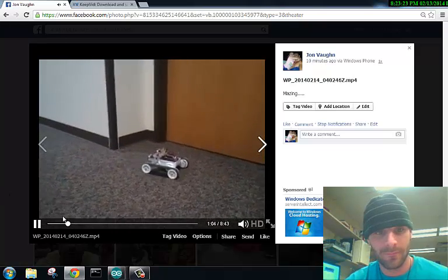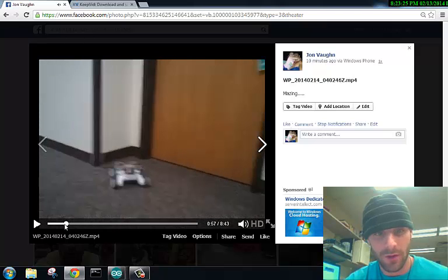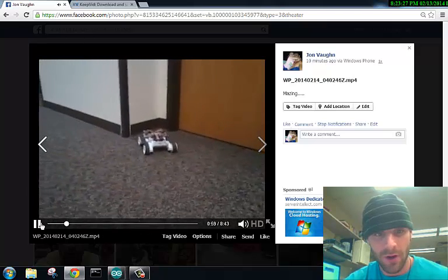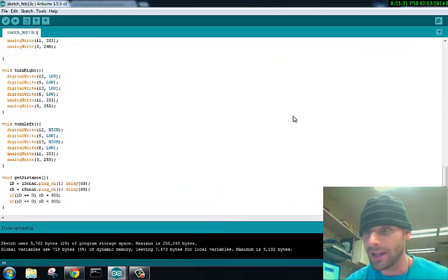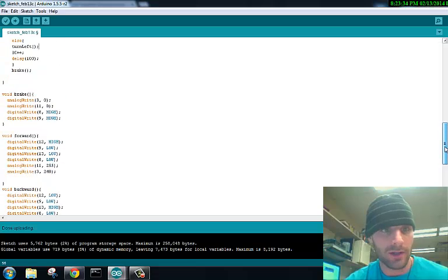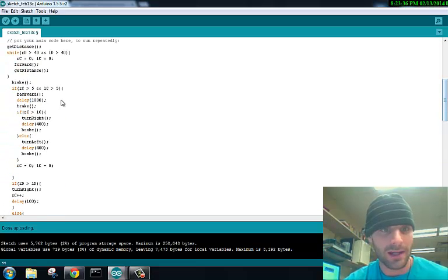There he goes. Now look right here and I'll show you what's going on. So you see how he's rocking back and forth there? Well, that's what this code up here does that I showed you. This code up here checks if right count and left count are both greater than 5. It checks exactly for that rocking distance.